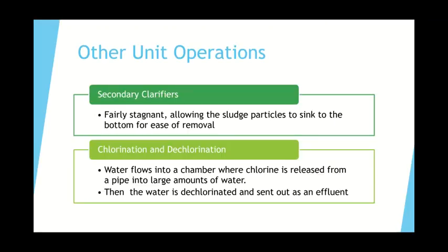The other main units used throughout the wastewater treatment process are the secondary clarifiers, which is where the activated sludge from the 5-stage biological nutrient removal process is allowed to settle out in order to be removed from the clean water and recycled back into the fermentation basins. On average, about 60% of the activated sludge is returned to the process. Before this stage of the process, alum is added to the wastewater. This is to flocculate any remaining phosphorus so it will settle with the sludge.